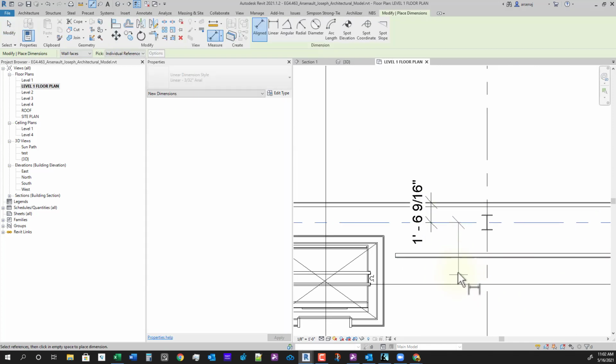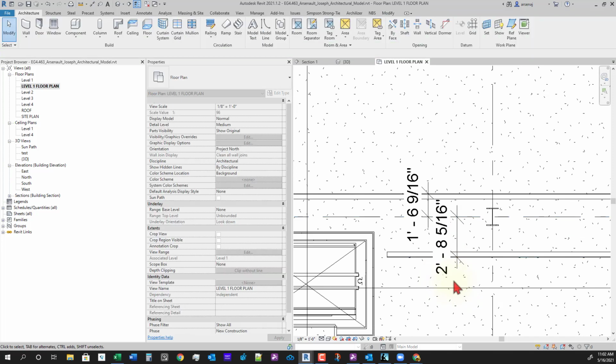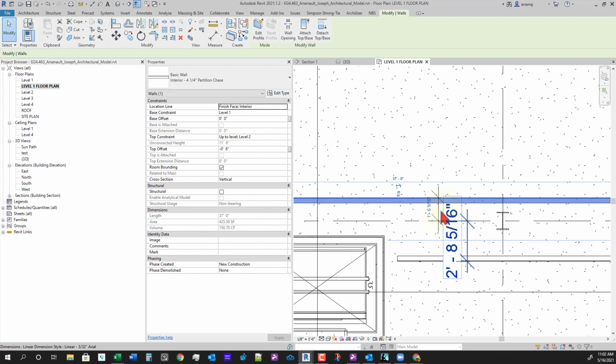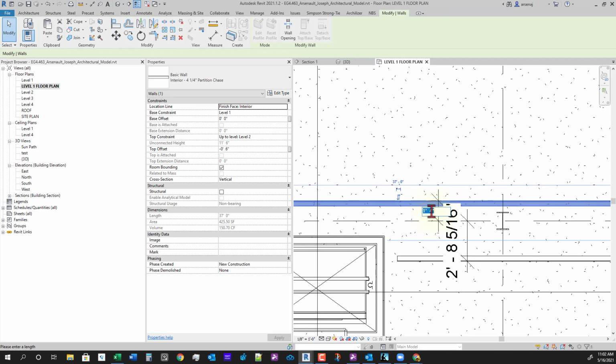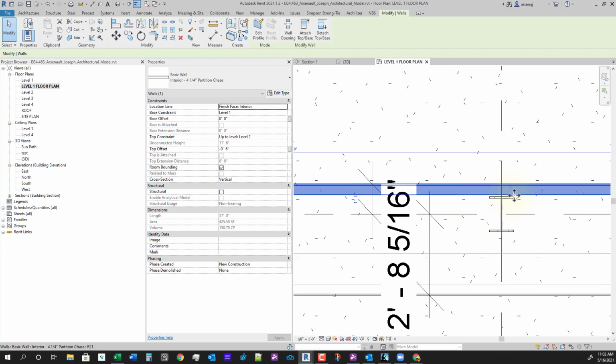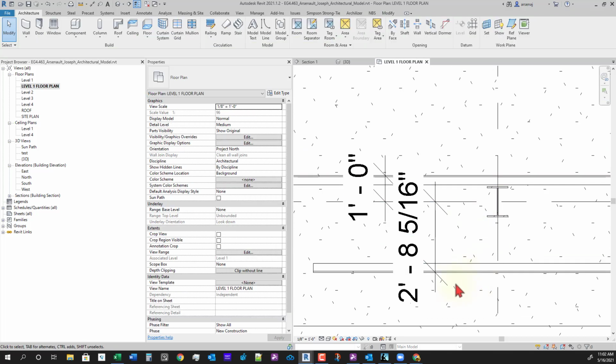And so the purpose of this wall is, again, plumbing, and it's also to cover up these columns. So let's throw another dimension on here. I'm going to make this wall, let's see, 1'4", I think should get us, actually let's do 1 foot. Yeah, so just at the face of this column, you can see we've got about 1 inch or 2 from the back of the wall.